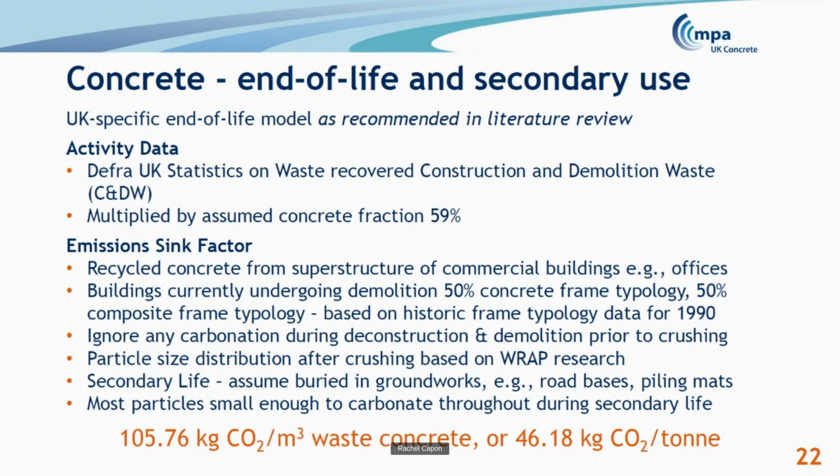So we assume that 50-50 mix, and we assume that nearly all the secondary life concrete goes into groundworks. We take into account, we subtract, the carbonation that's already occurred during the primary use life, but we do find a considerable amount of carbonation will occur in the secondary life, which is equivalent to over 100 kilograms of CO2 per meter cubed of waste concrete.